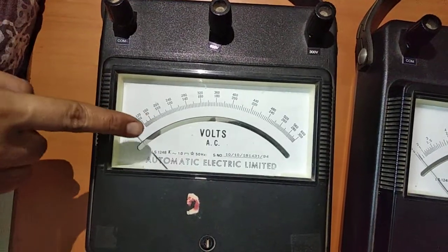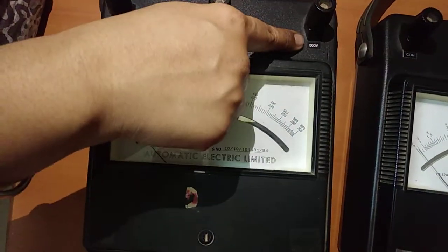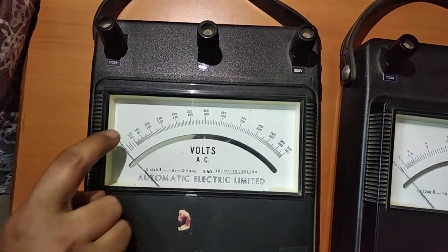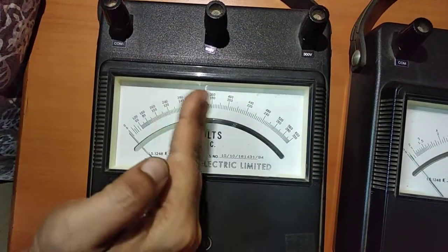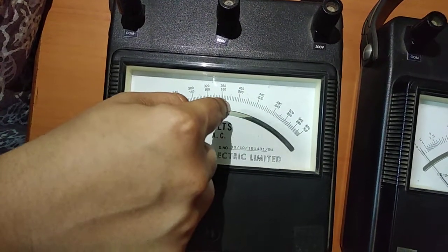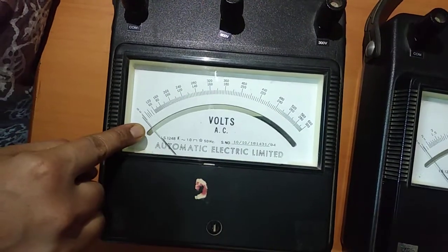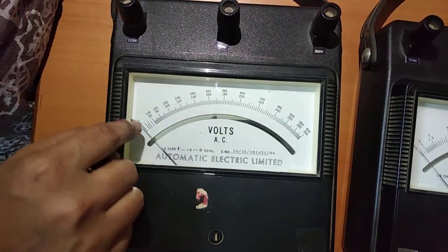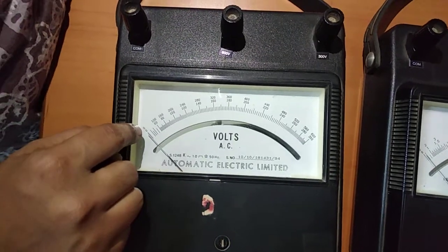So in the analog voltmeter, you can see, I told you that there are three terminals, isn't it? Common, 600 and 300. If we connect the terminals between these two leads, then you have to take the readings on the upper arc of the display meter. The needle will deflect and indicate a point, and you have to mark the point at which the needle coincides with the reflection in the metallic strip given here. So you see a metallic strip here, isn't it? Whatever reading it corresponds to, you will have to take that reading into consideration.